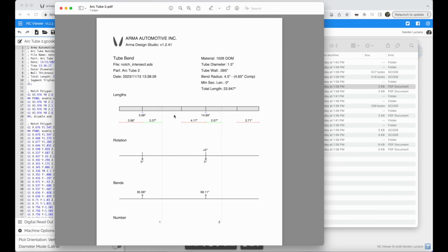Bending manually will just require careful consideration, because each of the bends will have a natural spring back depending on the type of material and a few other elements. So you'll want to be careful to bend. You will need some compensation above this angle to get the result of this, but it can be done.